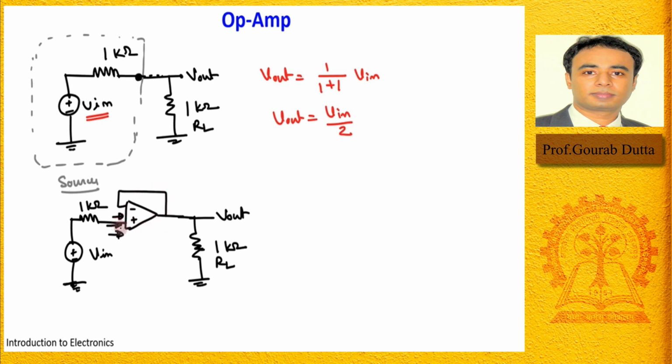1. So if this V in is here 1, what will be the output voltage in case of this particular circuit? In this particular circuit, this output voltage will be exactly equal to this input voltage, right? So there will be no drop across this signal source, almost no drop, right? So this is the use of this buffer circuit. Fine.